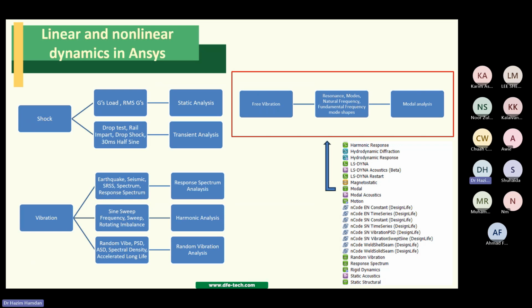Basically, for linear and nonlinear dynamic problems, we divide into three major groups, which are shock, vibration, and free vibration. For today we focus on free vibration, which is the modal analysis. You can see here, in the Workbench, there are systems that you can use for modal analysis.